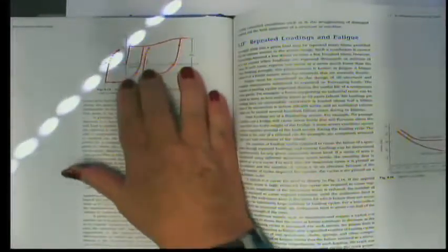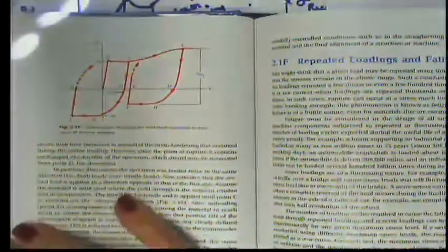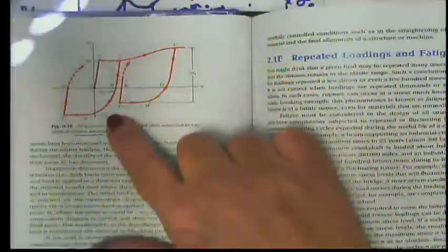Now, if you look at this, this is actually going to answer Dane's question. And the picture's a little bit better than I'm able to draw. So I'll go through this with you. Basically what we have here is a mild steel that we load and then we reverse load it. Reverse load means we put it back into compression after we've exceeded the elastic limit. So in other words, we start here at 0, 0. Okay.